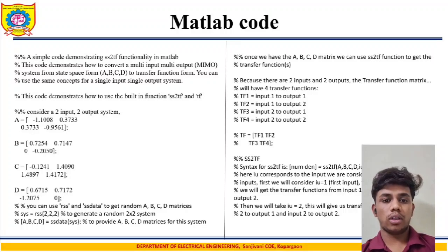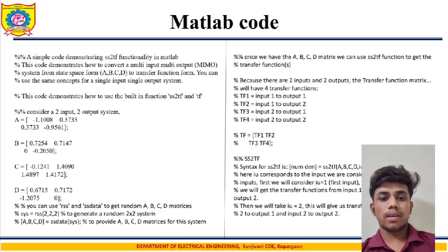And now talking on the output, after running the MATLAB code, we get the numerator and denominator for each transfer function. These are polynomials in s, and instead of ss2tf, we can also directly use tf to get the transfer function form. This makes the system analysis even easier.